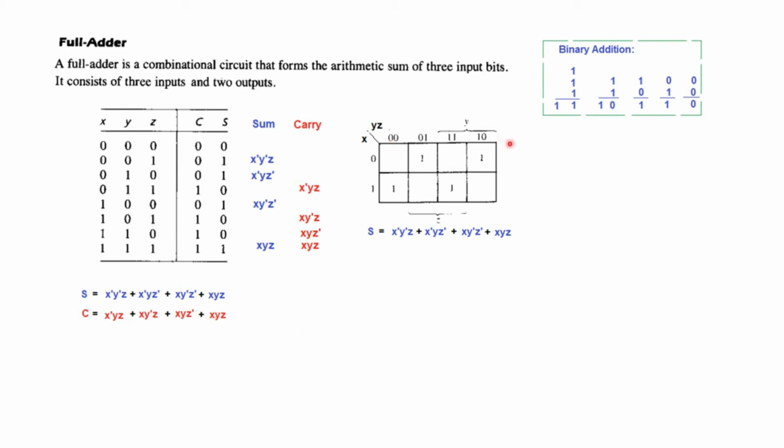So I hope you have learned how to draw a K-map. So we have 3 variables, so we'll write it x and y, z, 0, 1, 0, 0, 0, 1, 1, 0 and 1, 1. This is tricky. You have to remember that 0, 0, 0, 1, and then you go to the last one, 1, 0, and then come back for 1, 1. Okay. And now let's plot the sum.